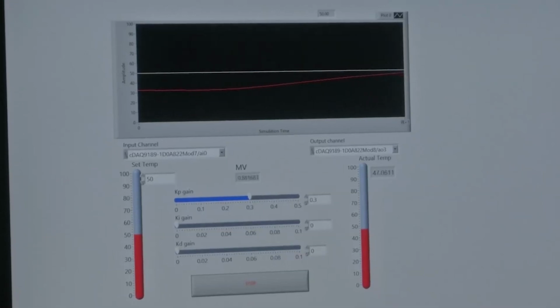So the time it takes to reach the set point entirely depends upon the gain that we have set. And because of higher gains, there are also chances of generating overshoot. Here we can see, because of the higher gain, it is pumping a higher amount of current, there is a little bit of overshoot. If that overshoot is okay, that's fine. If not, we have to go with smaller gains, or we have to go with a different differentiator, right? Also settling time.